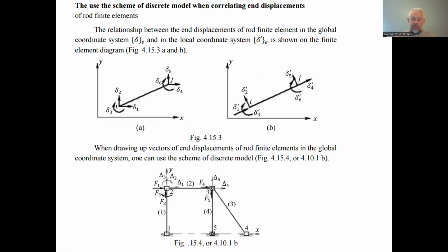So we have the longitudinal force instead of the horizontal force here. We can say that, instead of the horizontal force, we have a combination of the forces acting at the ends of the finite elements. One is the longitudinal force applied to the beginning of the finite element, delta 1 stroke, and delta 4 stroke, the same longitudinal force applied to the end.